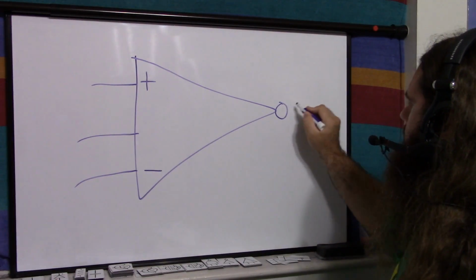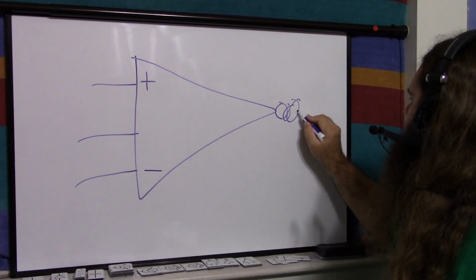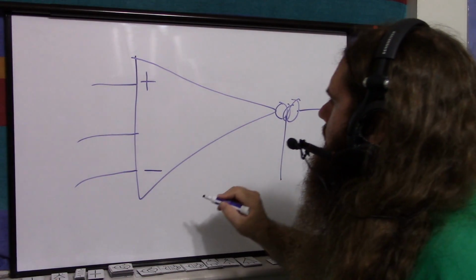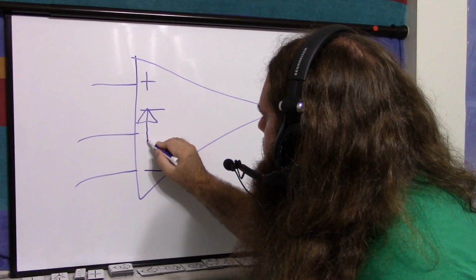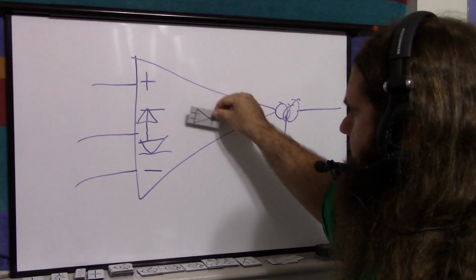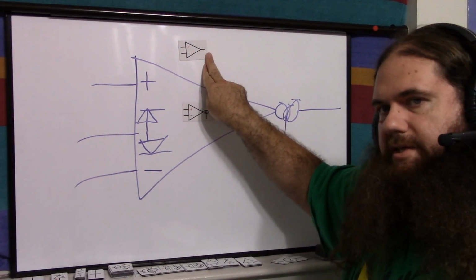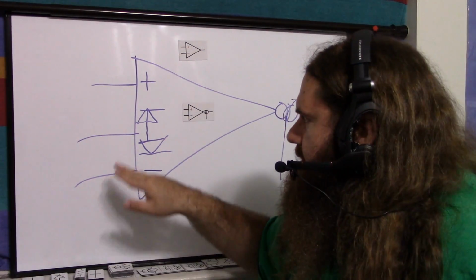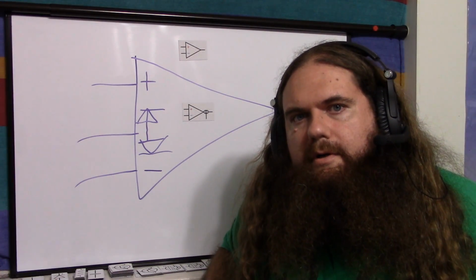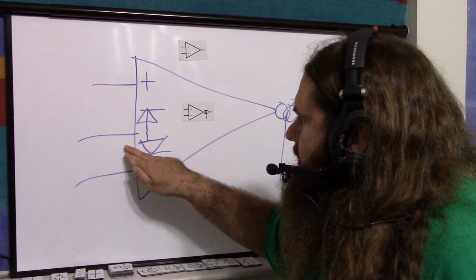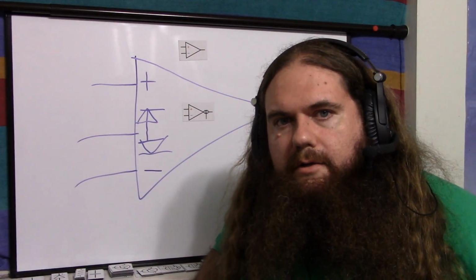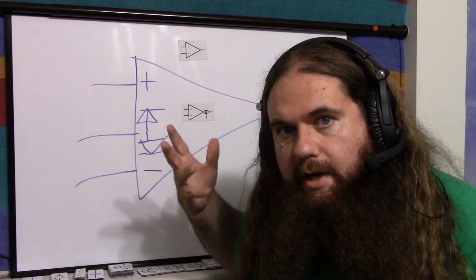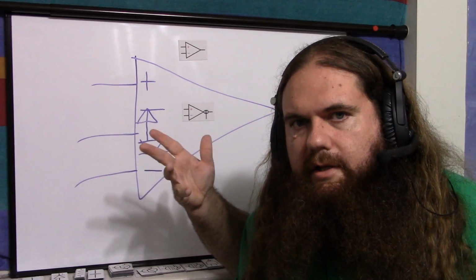You've got your 2 circles that are supposed to overlap, and then down here and down here, and then you've got 2 diodes, and they look sort of like this, whereas this is the symbol I'm using, which is very similar to the op amp on purpose. The reason I have not bothered with this is it's not part of the OTA. This is something called linearizing diodes, which don't have to be there. They are nowadays because technology has advanced.